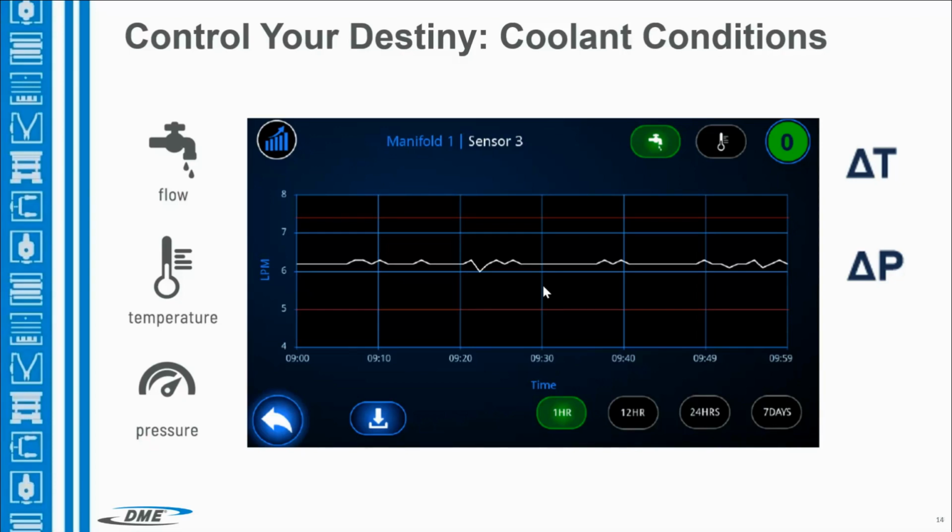I know it's probably not the most economical to monitor 140 water circuits or whatever you have, but get back to that design review you did with the part designer and the tool designer, and you can establish the critical circuits and really hone in on the control of those circuits, especially the restrictive ones. Those are the ones you want to make sure you have monitored and controlled. That will be your early indicator of decay in your molding condition.